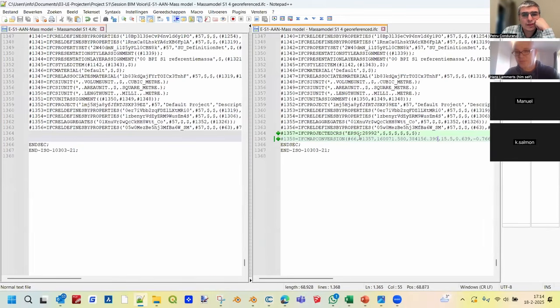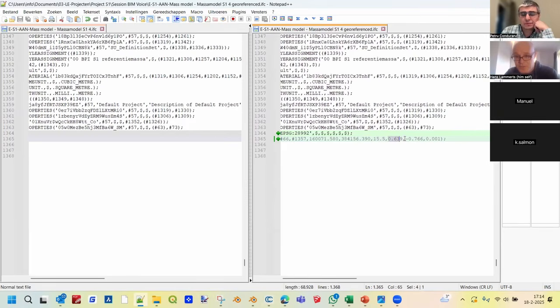This is being programmed, and this is the X and the Y. This is the height we saw, and this one is for the rotations. These two. And this one is for the millimeters to meters, times one. But these two, this is not like a rotation as you used to do with degrees, but it's like the horizontal of P and the vertical of P. You can look it up in the IFC schema.